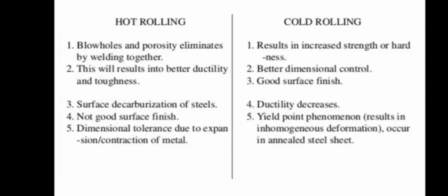Hot rolling results in better ductility and toughness in the material. In cold rolling, strength increases and dimensional control is better. You will have a good surface finish in cold rolling, and ductility decreases in cold rolling.